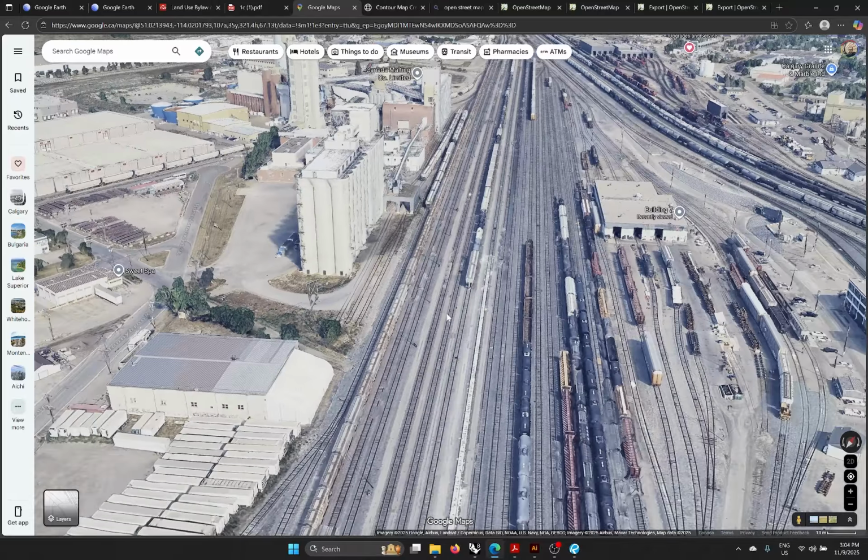So what we'll be doing in OpenStreetMap is going to the export tab or ribbon and defining our own area. So I'm going to manually select a different area. My site is right about here, so I want to select just a bit more outside of my site so that I know that when I create my 1:1000 site plan, it's going to be captured within this frame.